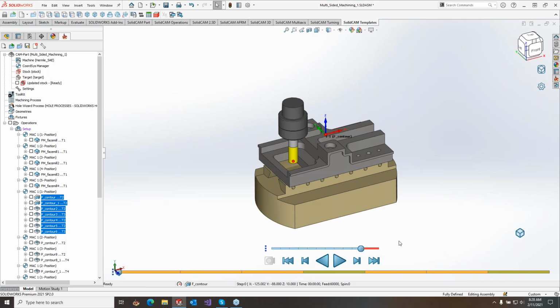For 2.5D parts, turning parts, there's really no meaning to use the red portion here. But if we're doing 3D, HSM, maybe even some large 3D iMachining toolpaths for sure, the simulation plays much faster here. And we mark them in red, so that way you know you're in multi-core and the simulation will play a bit choppier. So if I just play the simulation, we can see we can change the slider position.